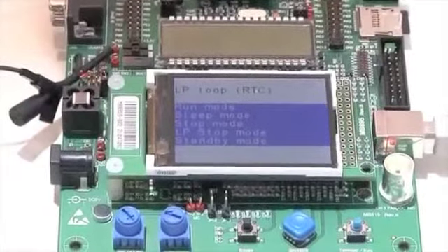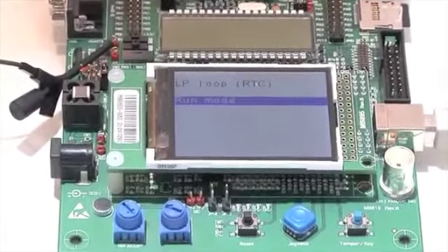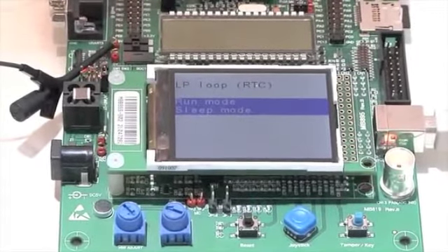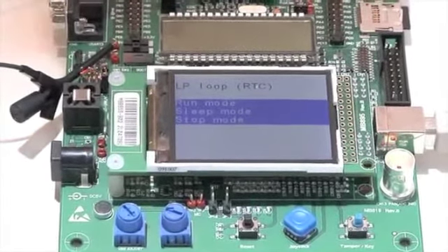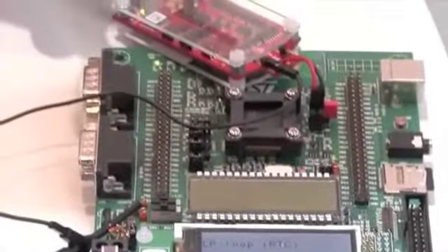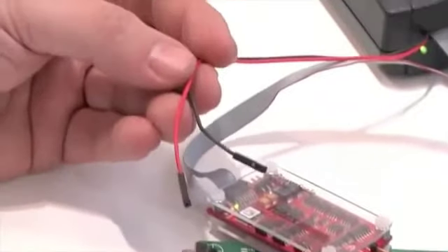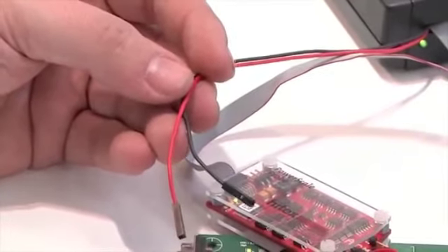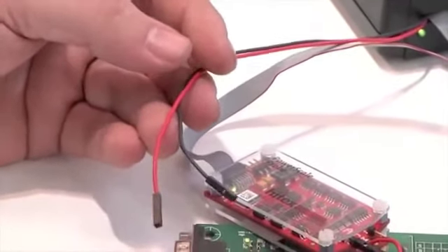So that you can then correlate back to the information that you see on the screen, giving you the instantaneous power consumption measurements. You're also able to use trigger lines to go from the micro back into the Powerscale box, which allows you to link directly to the routine or the program counter mechanisms that are inside your software, so you can see exactly which routine you were in for a given power consumption measurement.